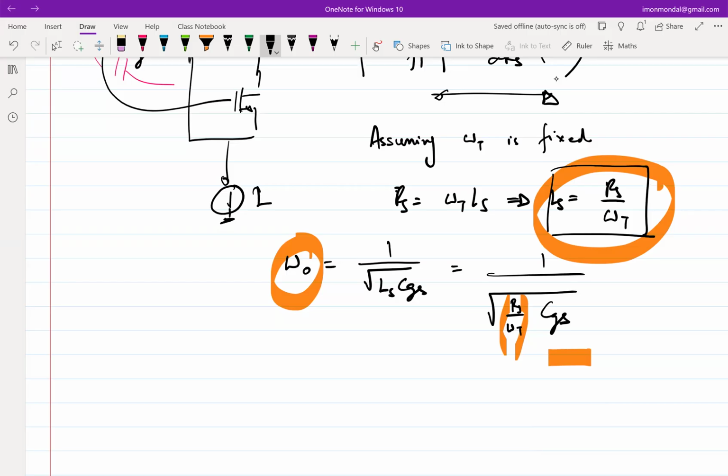So whenever you have these type of problems in circuits, you essentially are telling yourself that I need another variable, another handle. In RF, the good thing is that if the thing you are trying to optimize or fix is a resonant frequency, you can always place an additional inductor or a capacitor somewhere and then move it around while ensuring other things are not getting affected.